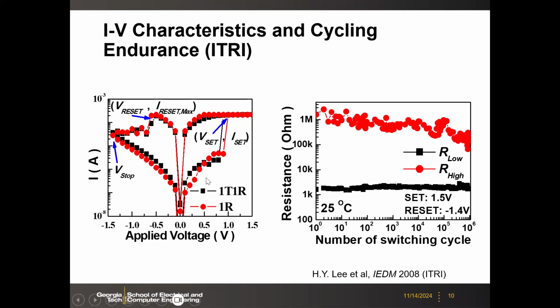So anyway, here you see this bipolar switching, and the switching voltage is kind of low because of that titanium helped to create the oxygen vacancy. So then you see that the turn-on voltage is like 1 volt.